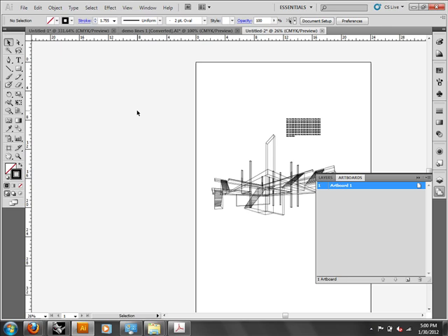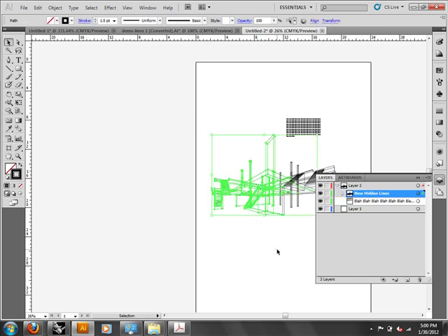I have one question about Illustrator. Sometimes when I'm selecting a bunch of lines together, I don't get that bounding box with the handles on the side. That may be because that layer is white. It's there, but it's white, so you can't see it. So you just need to change the layer color to a color that's visible on the white artboard. Otherwise, check to see if things are locked, things like that.